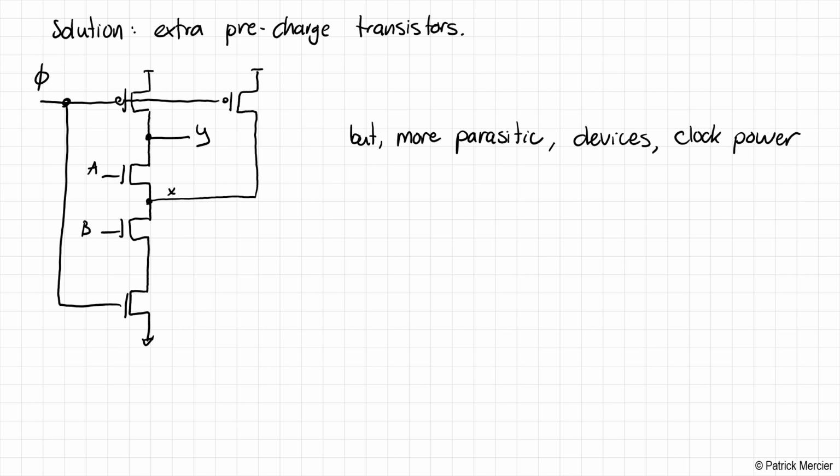Now the other solution that we could have done is let's just make sure that Cy is much larger than Cx. And nominally that should be the case, right? Cy has the extra PMOS attached to it. It's driving a load and so on. It turns out that that load in domino logic is usually just one inverter, so it's not a huge load, but it's definitely a load nevertheless. So usually Cy is larger than Cx. And we don't have to do this sort of thing unless in very special circumstances. We are introducing it in the lecture because this can and does affect dynamic logic. And so if it does, be aware that this is A, a problem, and B, there are some solutions to it.